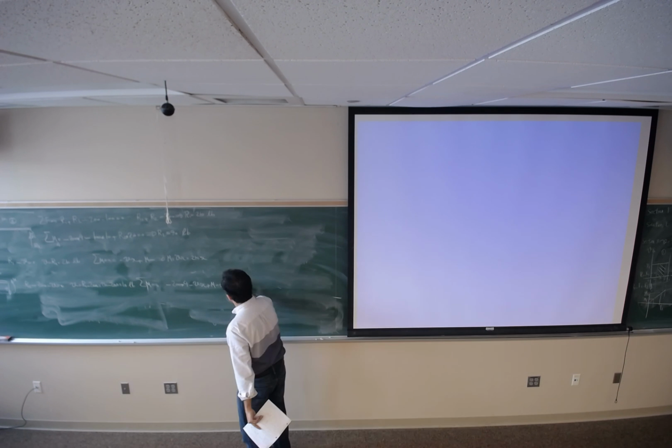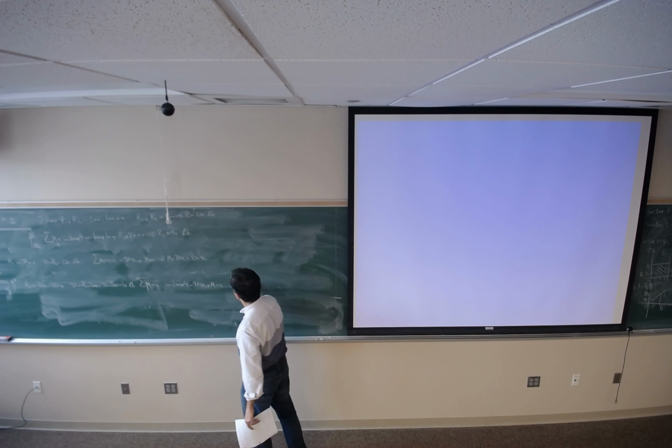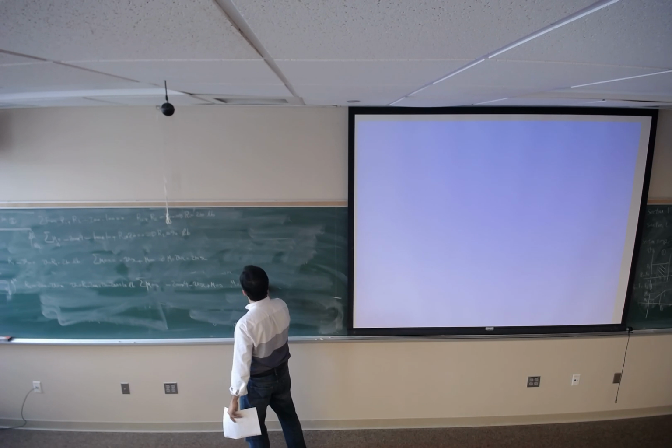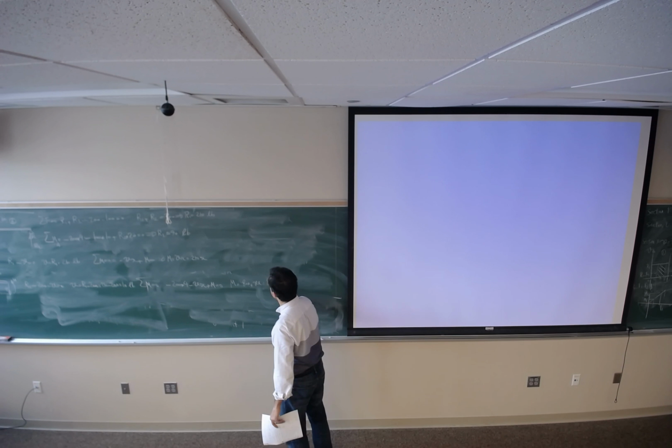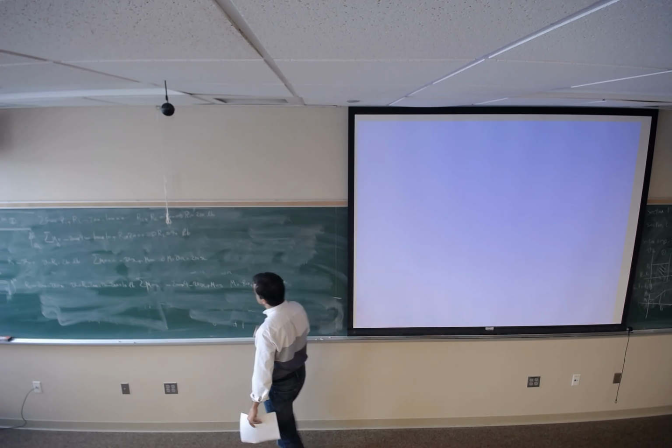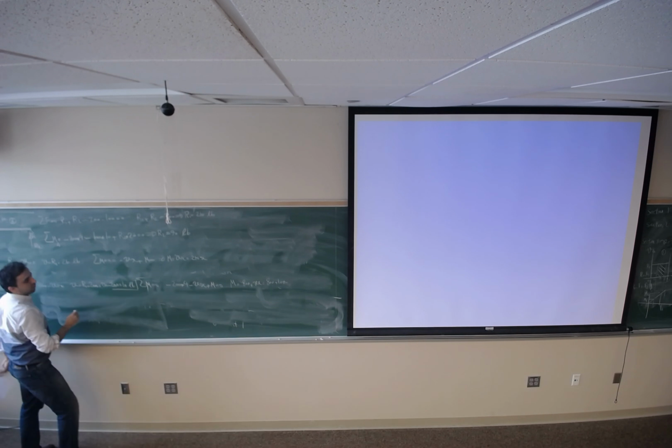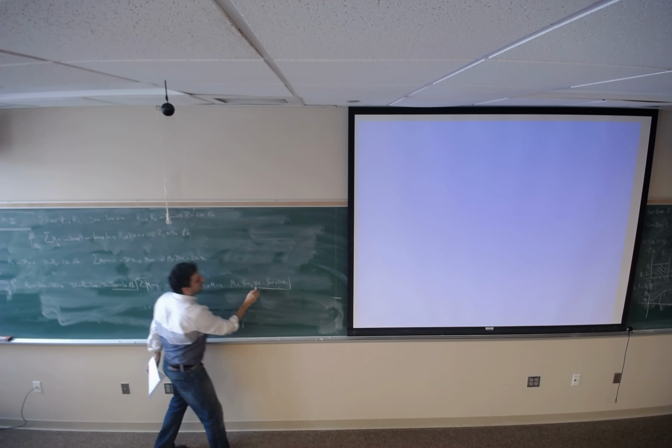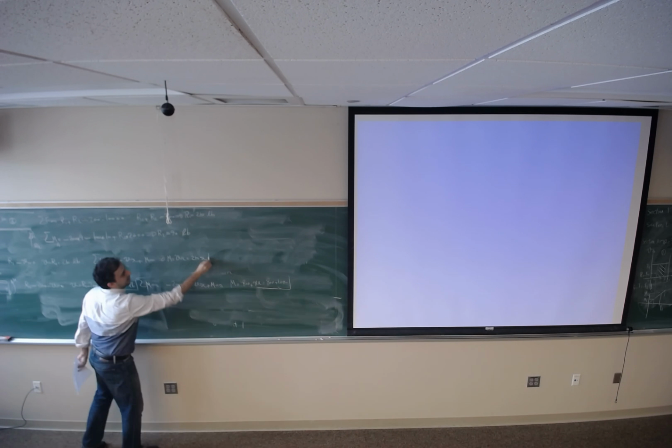I'm looking for M. M would be 800 plus V times x. V is 10, so 800 plus 10x. So I could find the shear force and bending moment equations for the first two sections. Now I cut the beam at section 3.